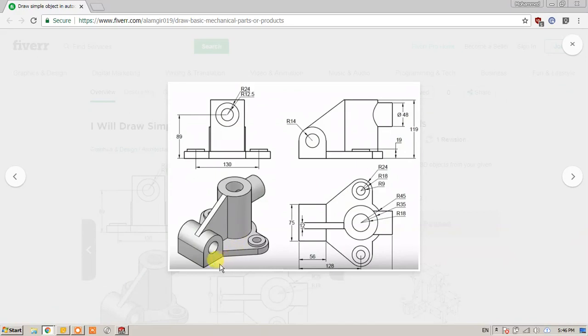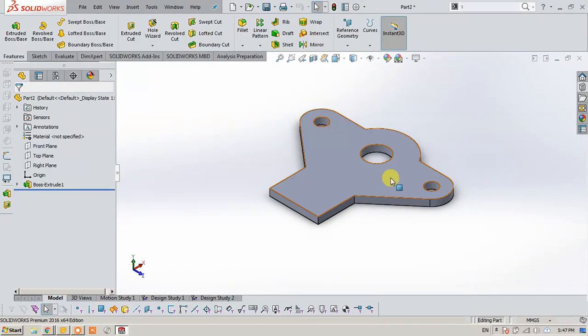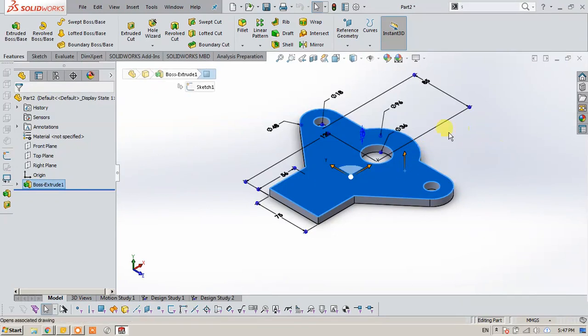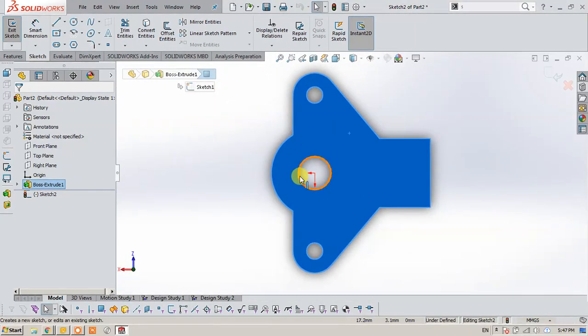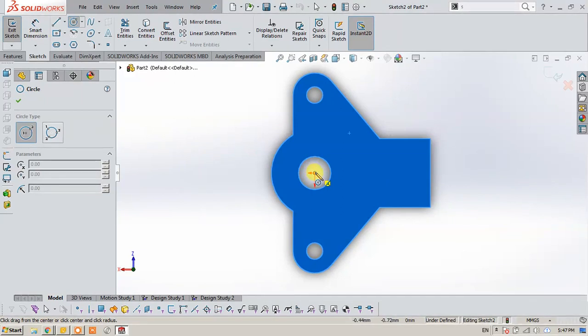We have the base. We now need to do this one and then this shaft right here. For this shaft, we have the inner circle already made. We just need this circle, which is about 35 millimeters in radius. So we hit this face. Once we hit it, we have this menu right here. We have edit sketch, which is the original sketch from which we made this one, or we have new sketch, and then space. Choose the view that's more natural.